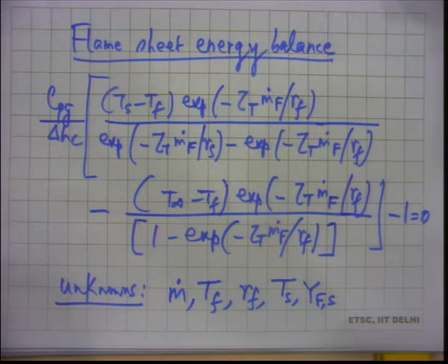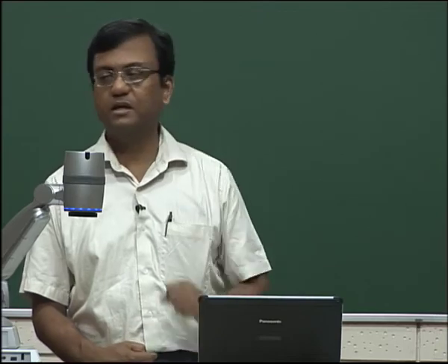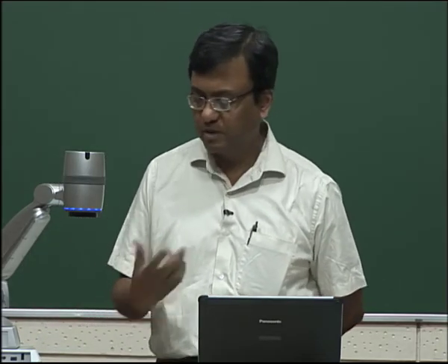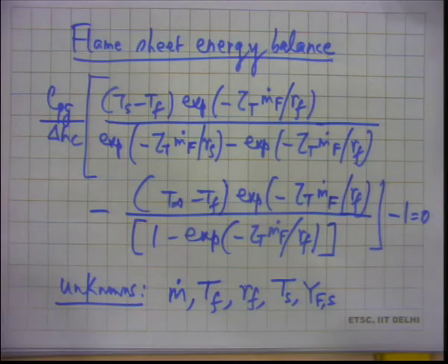When we try to find the droplet lifetime, how did we do that? We said d/dt of the mass of the droplet equal to minus m dot. We did that for droplet evaporation. So we will do something like that. That will bring in this time. As of now, it's as if you have a droplet of radius RS, and corresponding to that, we are getting all this profile. RS, of course, changes, but that is not explicit in all this. That will come later.